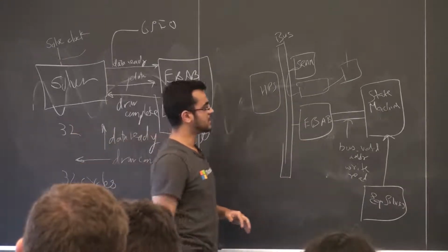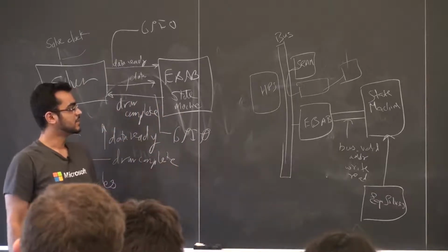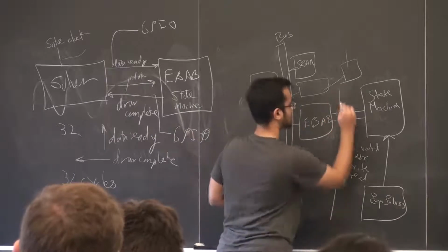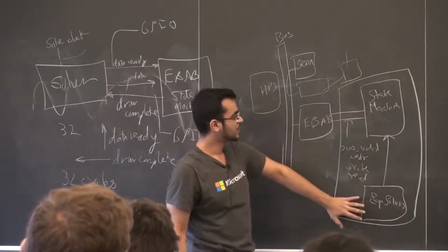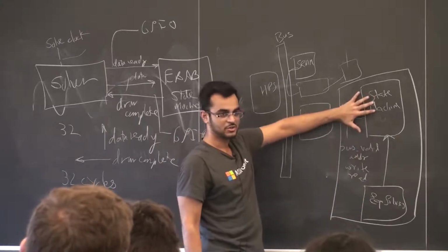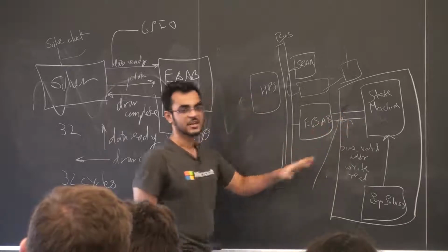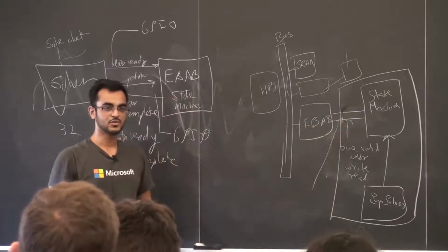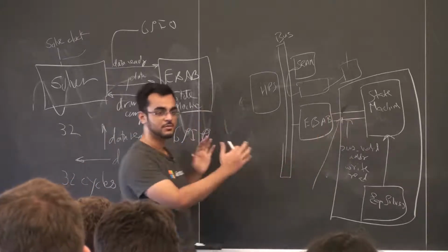So instead of directly hooking everything up and directly watching on the monitor, I would build a separate module combining the state machine and the equation solver, write a test bench on top of this, and monitor the transactions going on this interface. Suppose as soon as you come out of reset, you should blank the screen.